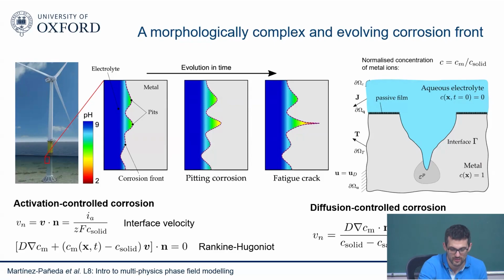That's no problem. Similarly, this model will work only if we have pitting initiation happening in the chloride environment. You're wondering whether you can nucleate a pit with the model as well? Most of the materials we are using are basically aluminium based, for aerospace for example, and they tend to have a very thick passive layer of alumina. So again, these models won't work there if passive film formation is taking place, because it is not taking the passive film into account.